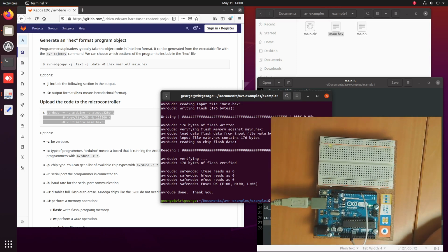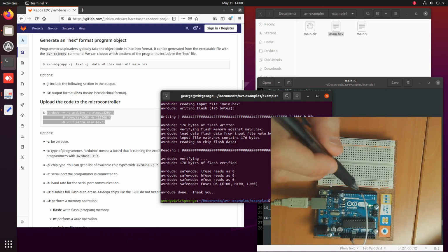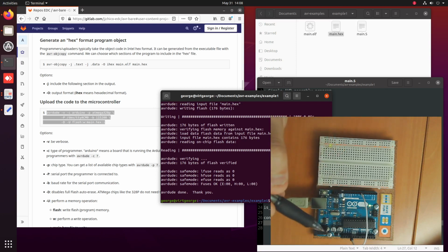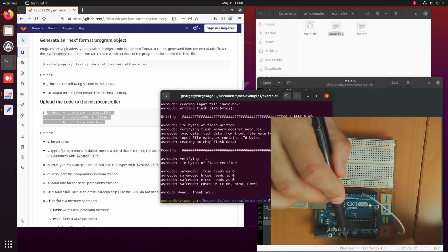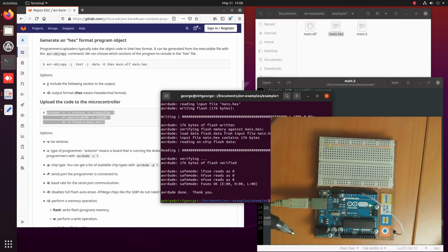But one thing that we can do with the Arduino boards is that we can configure it with a pull-up. We can tell the board to connect a resistor internally in the chip, so that when the cable is not connected, it will be slightly connected to 5 volts, to the high voltage.